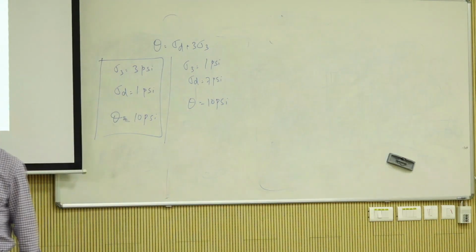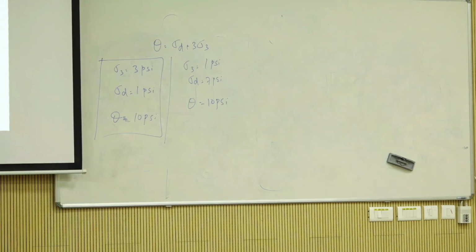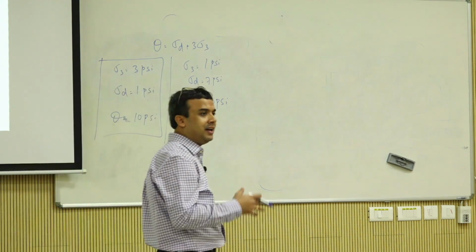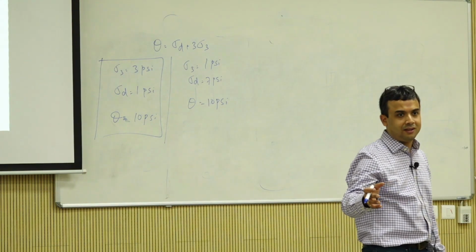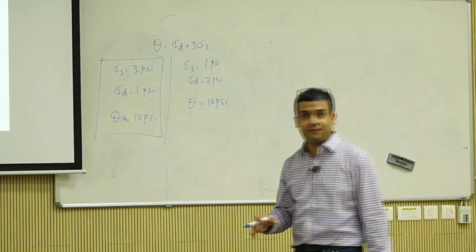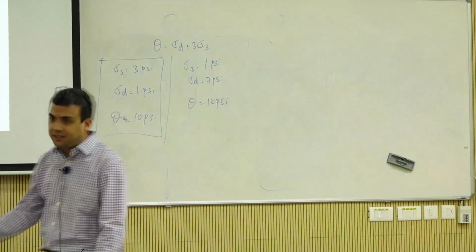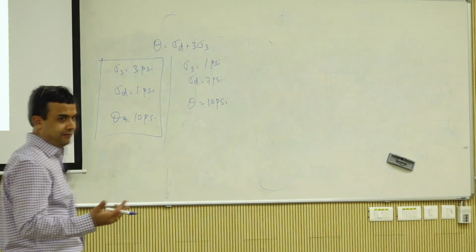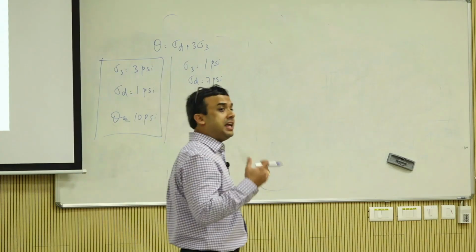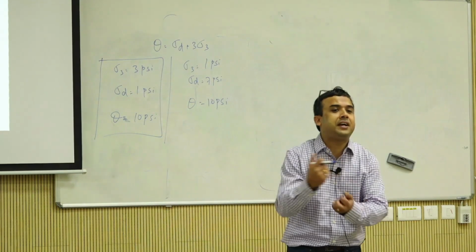Much more confined, right? So in the k theta model, you are not able to isolate between the effects of confining and deviatory effects. Do you understand what I'm saying? It works. The k theta model works all the time. It is the easiest model to use. It is the most common model to use, but there is a limitation. It doesn't isolate the effects, because the effect of confining versus the effect of deviator is different.